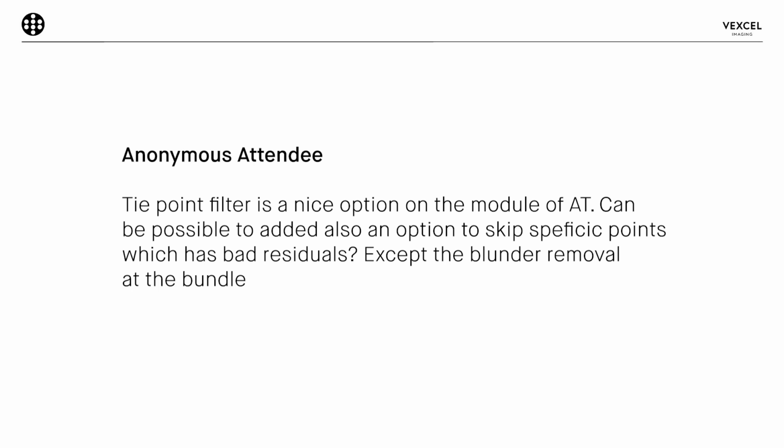Reducing or selecting these points can be done depending on the distance to the other tie points, or on the reprojection area, on the number of links and so on. So in the tie point filtering process, the algorithm does already consider also the quality of these points.